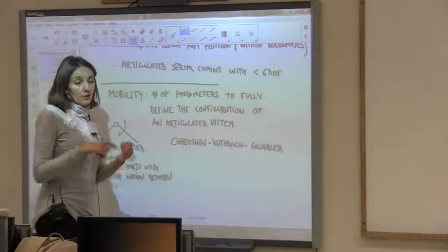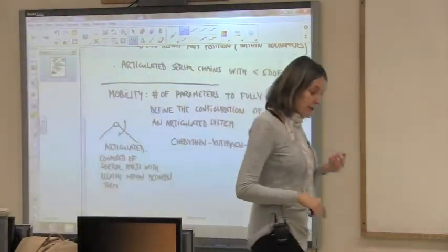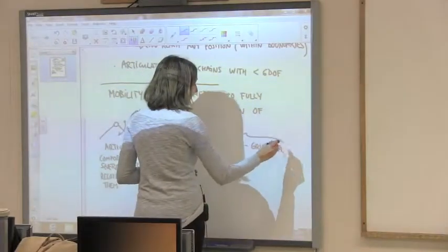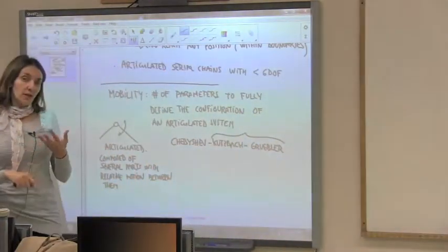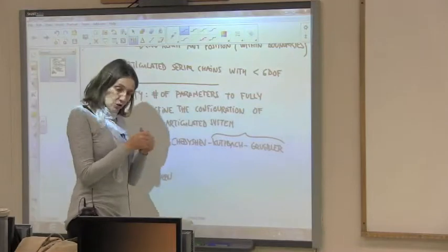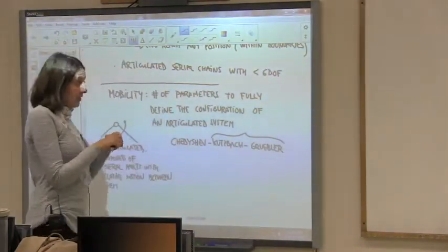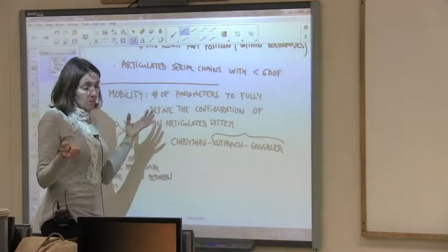And it consists of counting the number of joints, counting the number of links. That would be the Kutzbach-Grübler part of it: count the number of joints, count the number of links, see how much restriction each joint applies between two links, and you get a number.